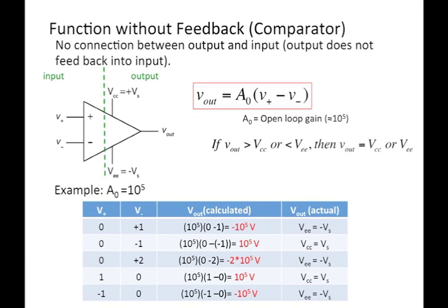There's some maximum power typically that you have to look up on a standard data sheet. But for us, we put about 15 volts on there. So plus VS is plus 15 volts, and minus VS will be minus 15 volts. That lets you operate between minus 15 and plus 15 volts.